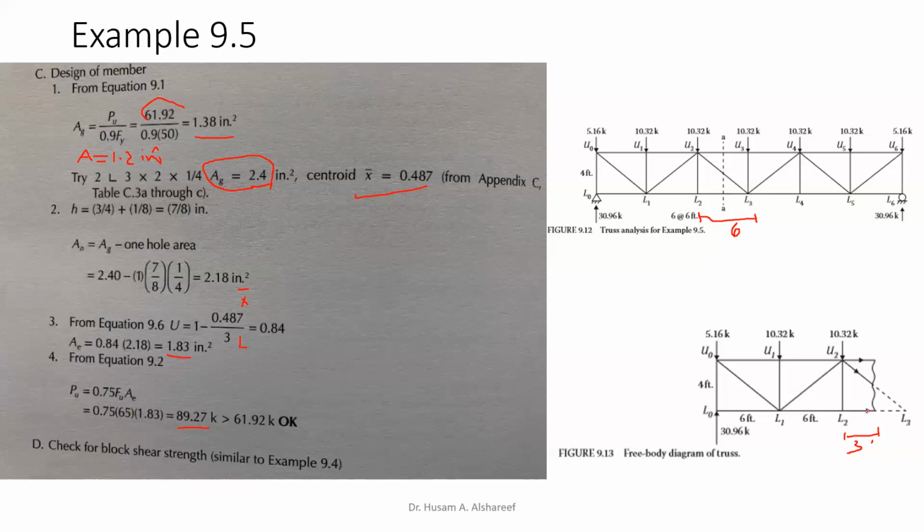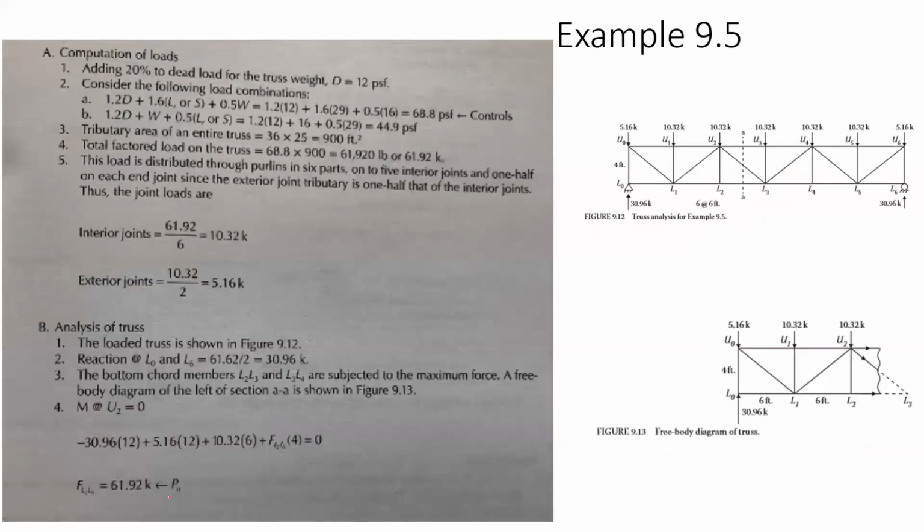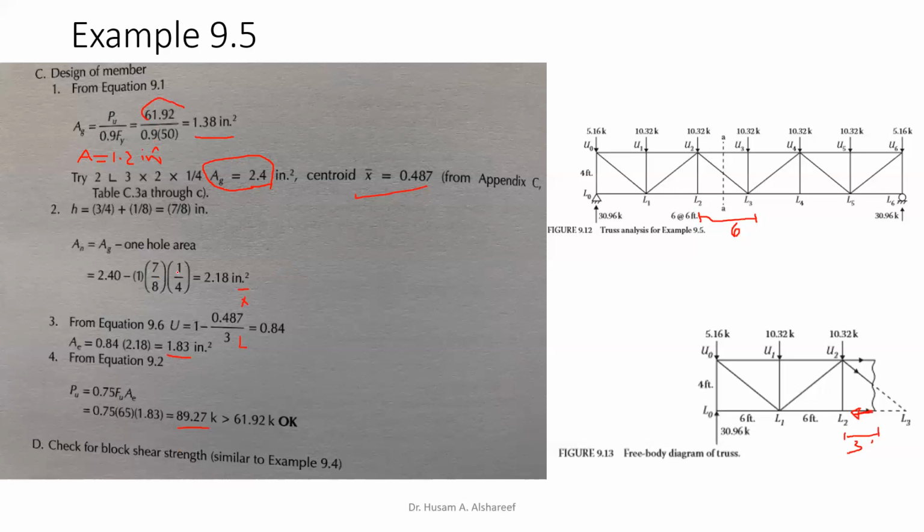Remember, this internal force has actually become compression. If I take you one step back here, see, it's compression. This arrow pointing in this direction means compression, it's not tension. So our value here is larger than the actual internal force that we found, so we are good. That means our design is adequate.